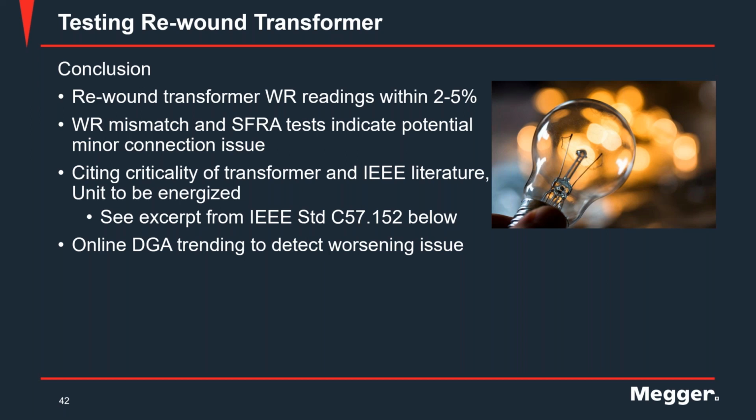And the customer is going to perform online DGA, and it's going to understand the signatures of its dissolved gases, and they're going to train them over time to detect any issue that might be worsening.